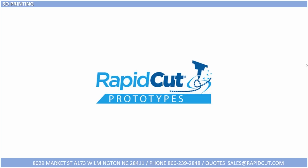It's going to probably be cheaper to get one of our rapid tools versus making a run of SLA parts. So that's, again, going to be project specific. The more complex the part is, the more it's going to lend itself to 3D printing for shorter runs. But if you're making a dog bowl, and you need 20 of them, injection molding is going to win. Give you a reference there.